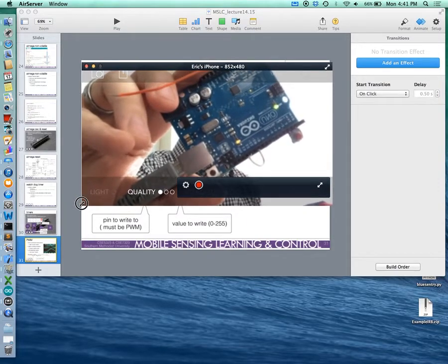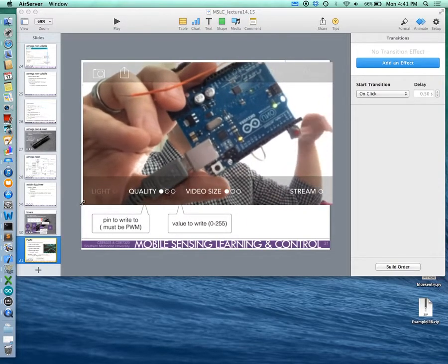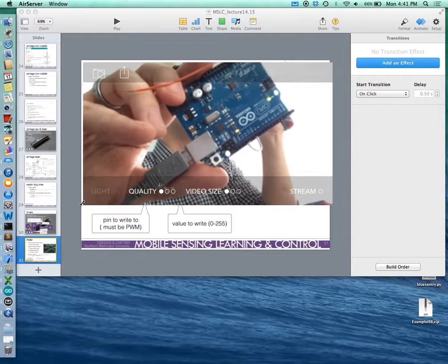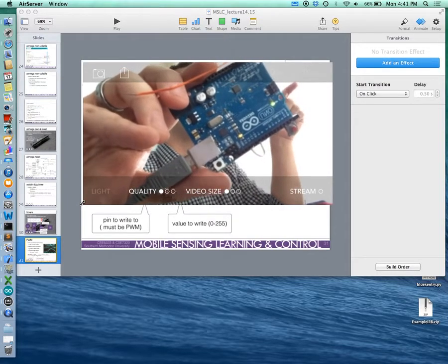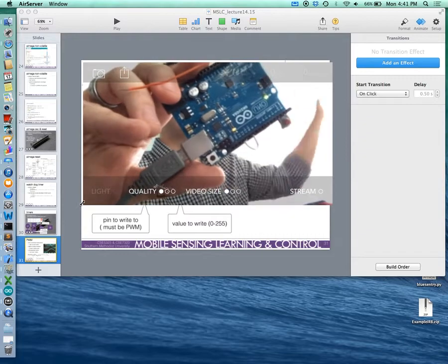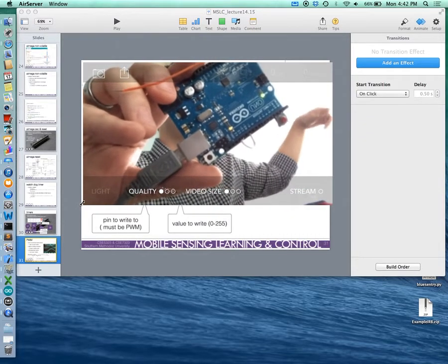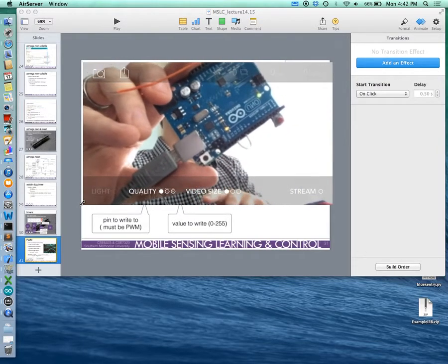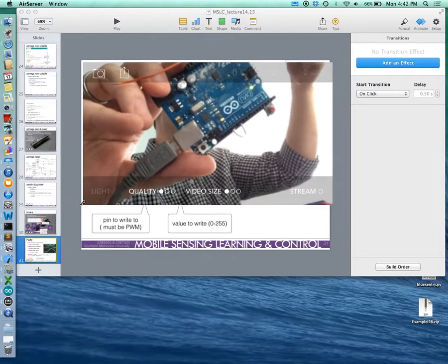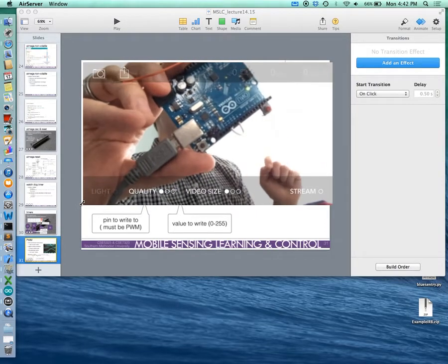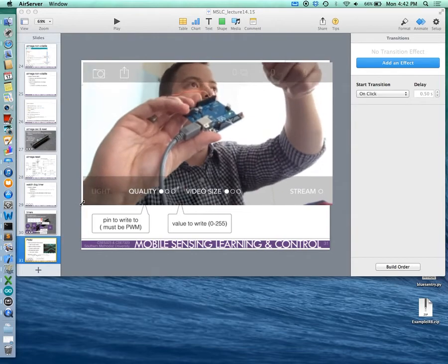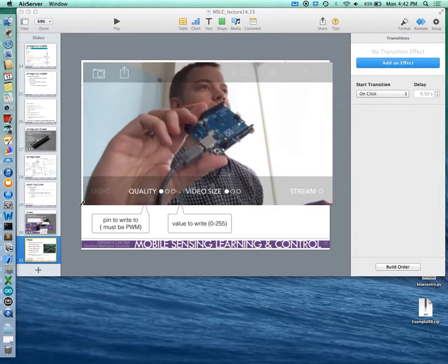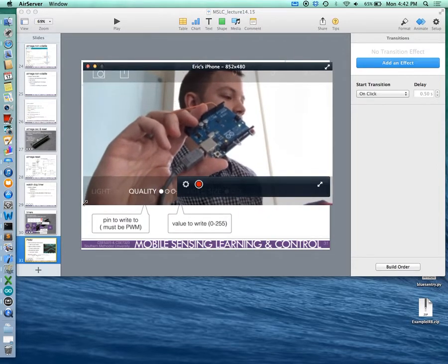Why did you have to do the wire thing? Oh, the wire thing? So pin 13 is a general purpose input output, but it doesn't have that pulse width modulation hardware on the chip, right? So I can't just set the comparator value and let the counter and stuff do its thing. So there's not an LED hooked up straight to 11? No. That's why I took the wire from pin 11 to pin 13 so that I could control that LED. I could have also taken an LED and stuck it in there and then taken a resistor to ground and controlled that LED, right? If I wanted to. But we might as well use what's on board the Arduino.